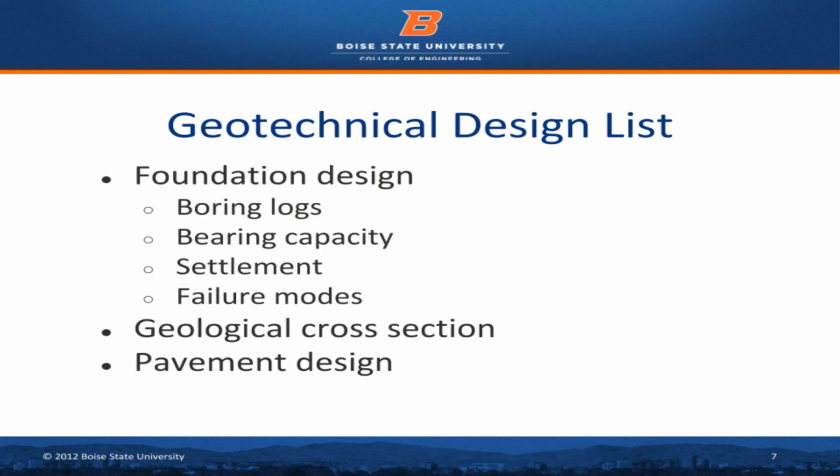For the geotechnical portion of this project, I received boring logs for the site, which were developed from standard penetration tests conducted at depths 2 feet and then in increments of 5 feet down to 25 feet according to Idaho standards. From there, bearing capacities, settlement, and failure modes were calculated for the foundation. Geological cross-sections and pavement was designed as well.